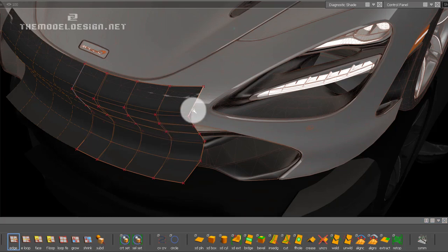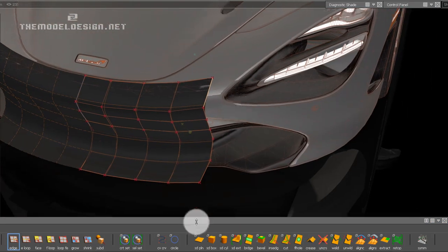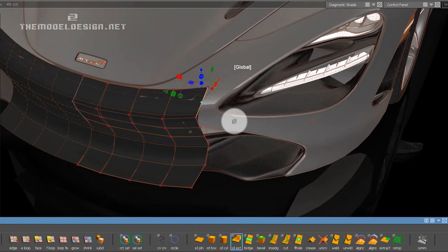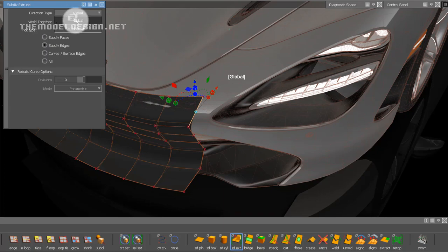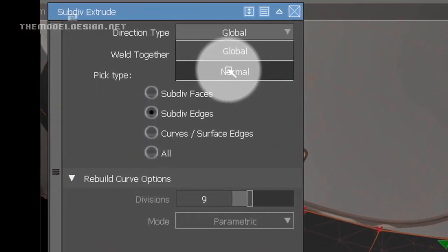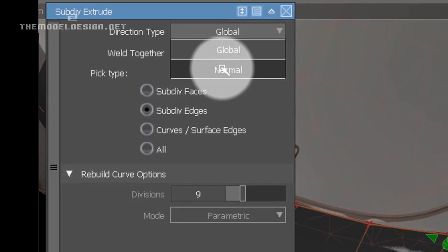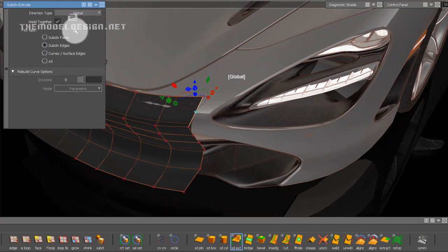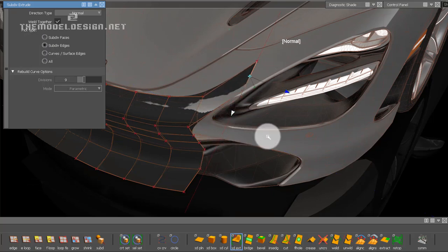Grab the single edge of this square and use the extension tool with the normal option on. It is basically like sliding, so you are creating new geometry normal to the existing patch, existing edge. By clicking the space button, you are ready to create another one.